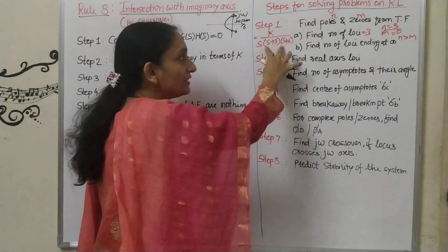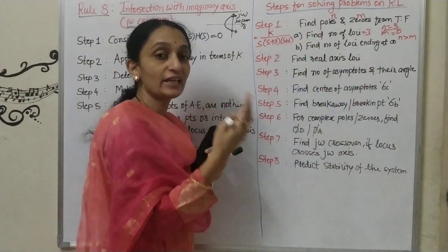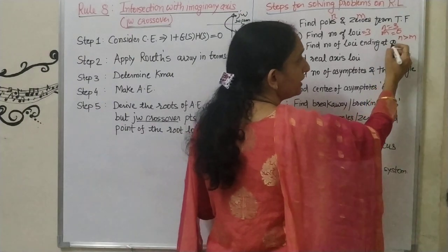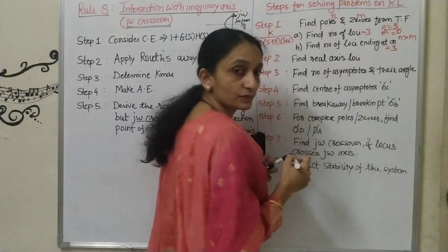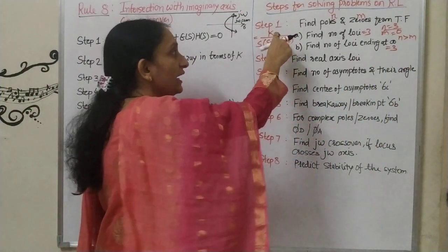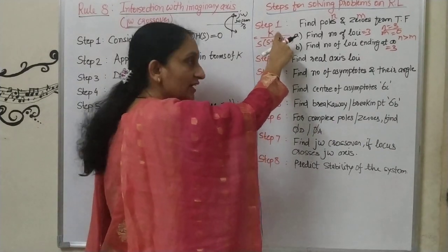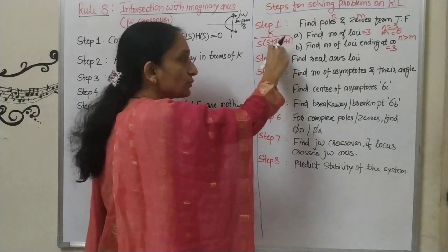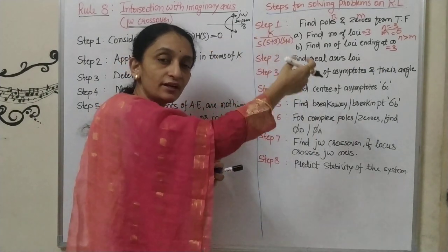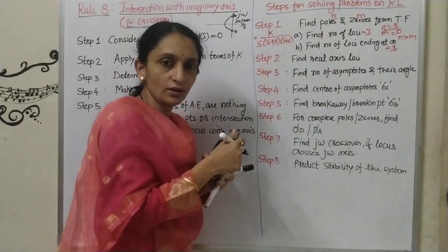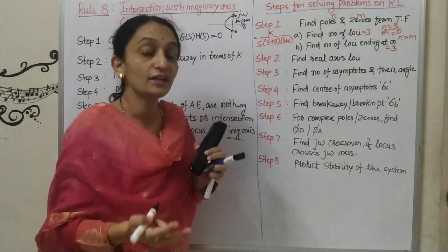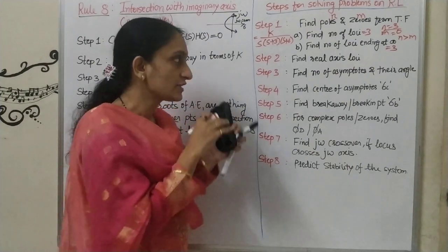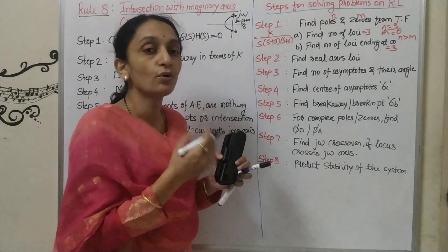Okay, so all these 3 root locus will terminate at infinity. So here the number of root locus terminating at infinity will be 3. See, suppose any zero is there, in that case out of the 3 root locus, one of the root locus may terminate on the zero and the remaining 2 will terminate at infinity, as there are no zeros to terminate. Okay, see, this point will get clear when we solve more numericals.